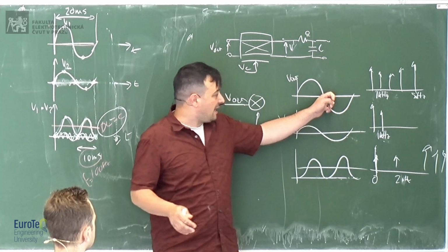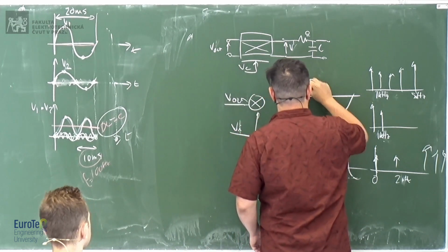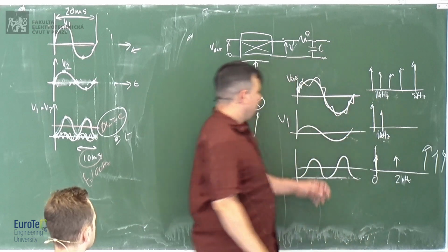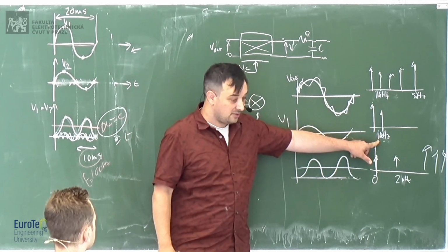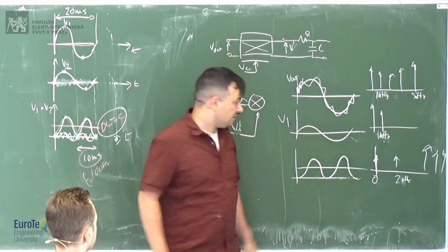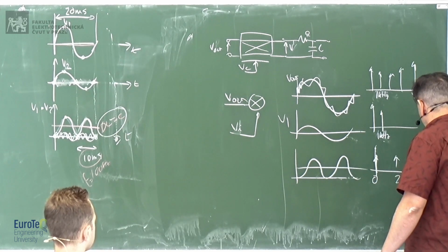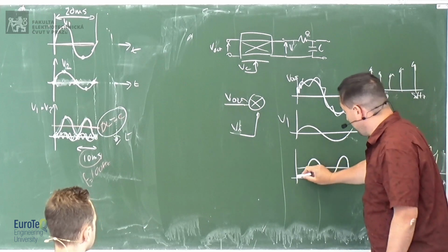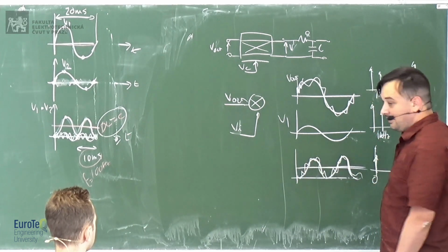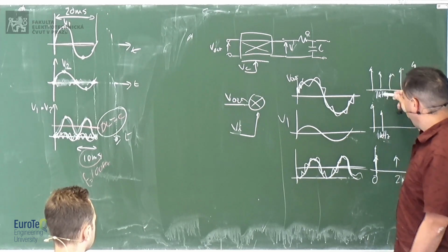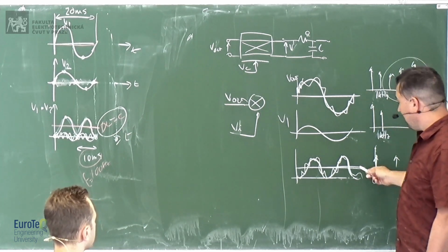Then, when you multiply, this signal will also have some 5 kilohertz disturbance added to it. But then you multiply times 1 kilohertz. So what do you get? 4 and 6. So you have 4 kilohertz and 6 kilohertz. Here, of course, there will again be some disturbance, but it will not affect the DC value. The DC value will be given only by 1 kilohertz times 1 kilohertz. So all this that you have here is not influencing the output.